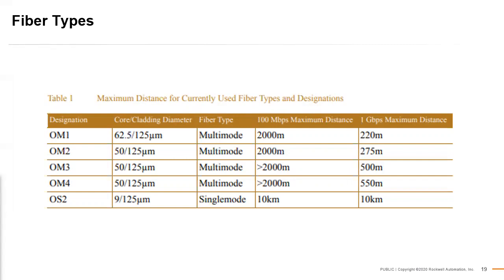And addressing the 50 micron multimode, the OM4 cable is backwards compatible to the OM3, OM2. Whenever you do your systems on your length, you're as good as your lowest common denominator. So if you have OM4 cable everywhere, but you're using OM2 patch cords, you would defer to the distance of your patch cords listed. So you'd be limited to, on a gig, 275 meters. Just keep that in mind.